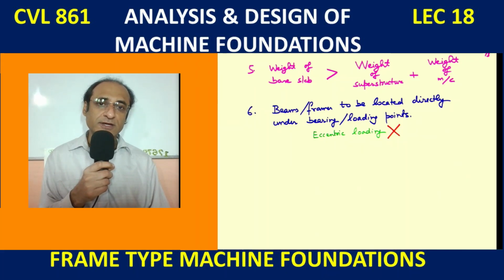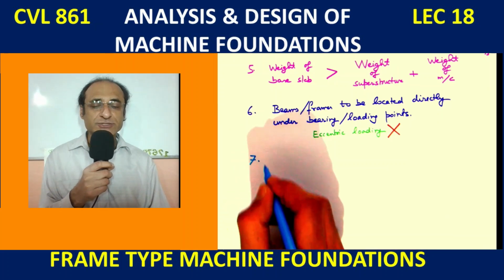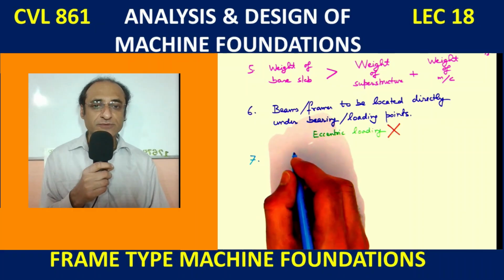And then the location of the loads should pass through the CG of the base, as in the case of the block type foundation.